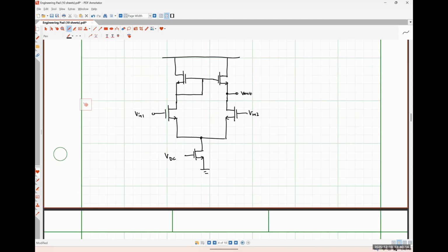And then we would feed it into a push-pull output stage, which will cause our output to be able to swing between our positive and negative supply rails. And guess what? It also happens to have a really low output resistance. So an op amp in and of itself is actually a 3-stage transistor amplifier in its most basic form.